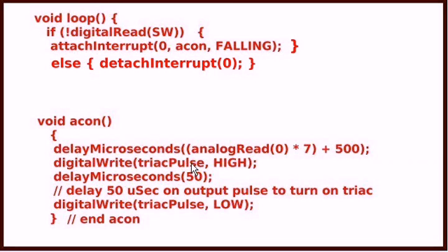That's the electrical signal that's sent to that optocoupler, goes high. I'll delay 50 microseconds, then I'll go low. The minute that I go high, I trip on that optocoupler triac combination to turn on the AC power. And then I turn it off.